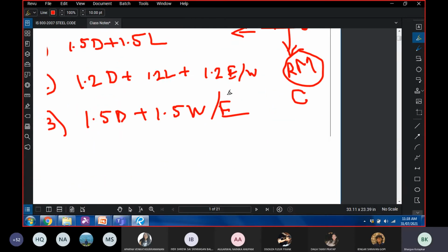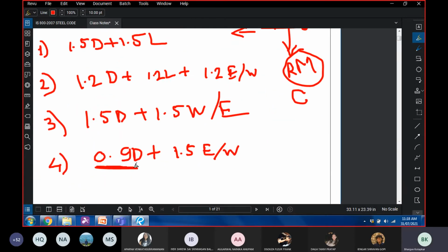And therefore, we underestimate the dead load by using a factor of 0.9. So the actual dead load is 1D and the underestimated value is 0.9D. For some reason, we say that only 90% of the dead load is really helping us resist that moment. And for that particular type of failure, we use this combination. And that's why we have a factor of 0.9 for dead load.